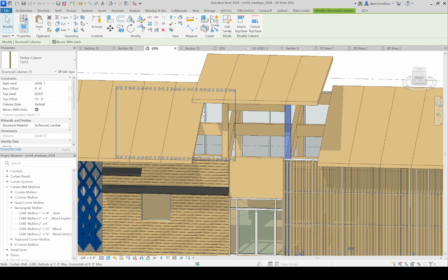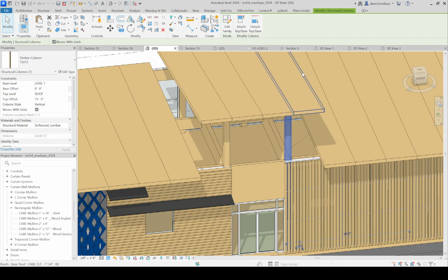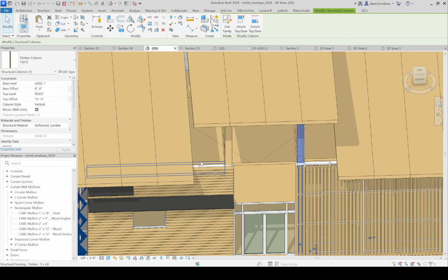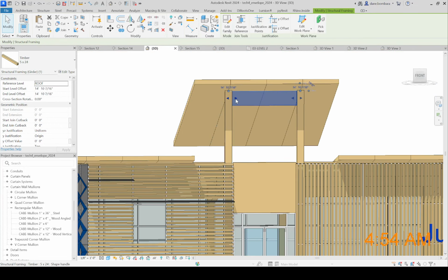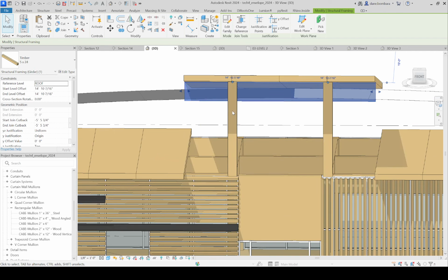Then I'm floating out here, meaning that this is kind of cantilevering out. So one thing I could do potentially is rotate the CLT and run a beam down the center and then rotate the CLT the opposite direction. So instead of going long ways, I could go short ways. So I could have two beams going over, and it would just cantilever at the ends. It's one option. If I didn't want to do that for some reason, I'd probably have to put another column. I'd have to maybe extend this beam out like this, and maybe they could cantilever that far. I don't know. Maybe Craig knows.